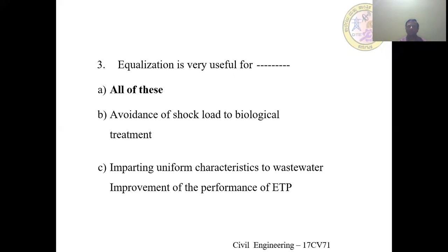Equalization is very useful for avoiding shock load to biological treatment, improving uniform characteristics of wastewater, and improving the performance of the ETP. It performs in all these aspects.